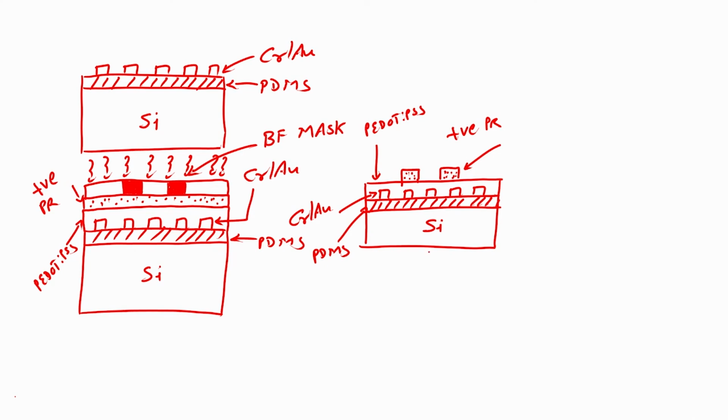Now, I have to remove PEDOT:PSS. So, I will use RIE to remove PEDOT:PSS. RIE stands for reactive ion etching, reactive ion etching.